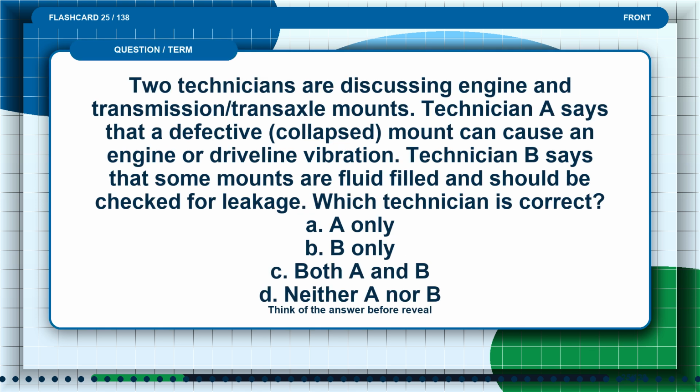Flashcard 25. Two technicians are discussing engine and transmission/transaxle mounts. Technician A says that a defective, collapsed mount can cause an engine or driveline vibration. Technician B says that some mounts are fluid-filled and should be checked for leakage. Which technician is correct? A only, B only, C both A and B, D neither A nor B. Pause and think of the answer before the reveal.